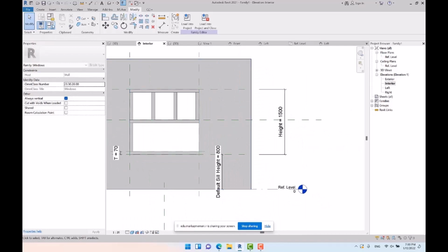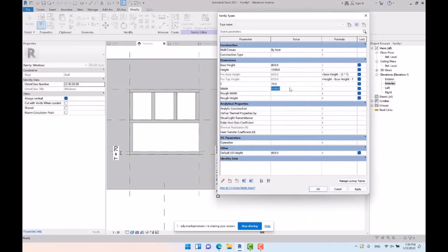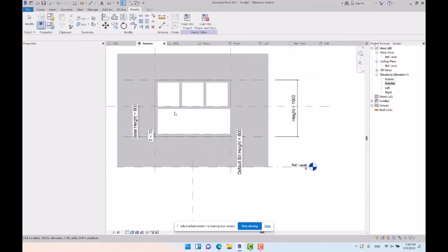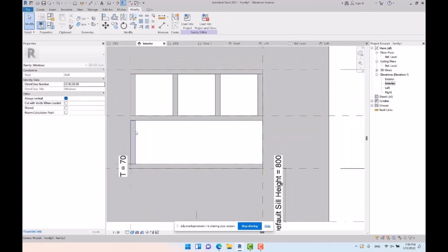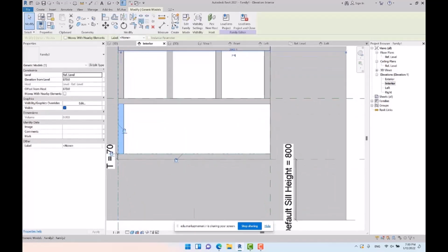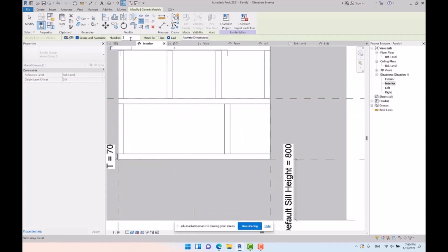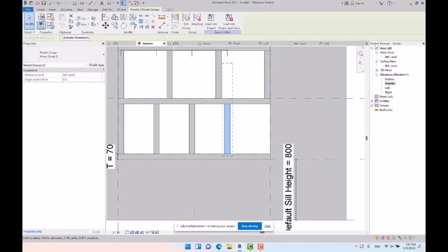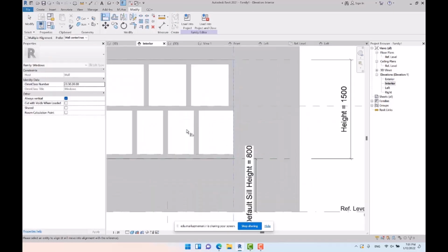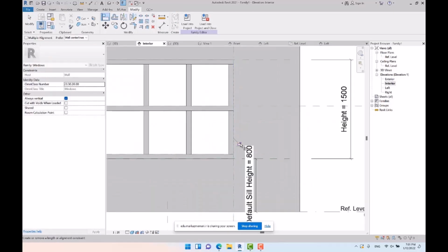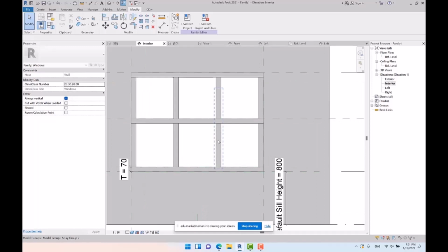And after that I open family types. Here if I modify the width to 2 meters for example, as you can see the distance between the profiles is adjusted too. But about the bottom part, here if I pick the array tool and then I move it to last, for example I place it here, and then I want to specify the number of the array, for example 4. We got the same process. I want to array the last profile to the reference plane, just like the top part, and constrained or locked.